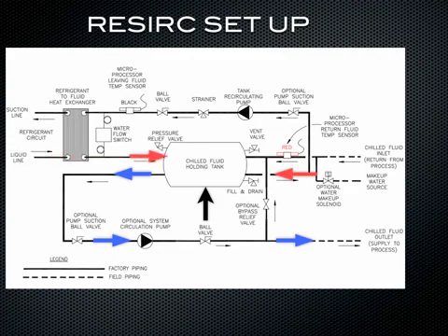It will pull that water through the recirc pump, and it will pull it to the chiller evaporator, which is this piece right here. And the heat will be removed over to the refrigerant side, and then you're going to have your desired leaving water temperature back to your tank to mix with that fluid. So you basically have 2 separate loops acting independently.